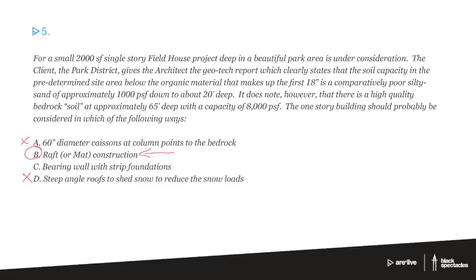It's going to be a B, and what that means is, instead of having specific foundations, I essentially just do a great big thick concrete slab that might be, say, 2 feet thick or something. If I have some bad soil underneath it, it doesn't really matter, because I get the entire square footage of the building to count as my foundation.